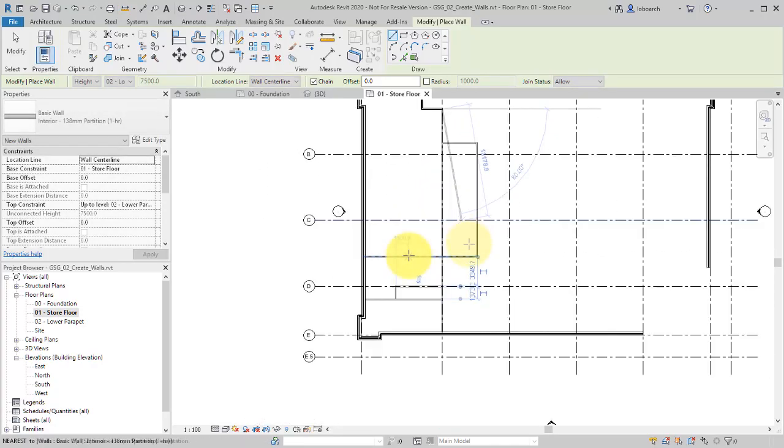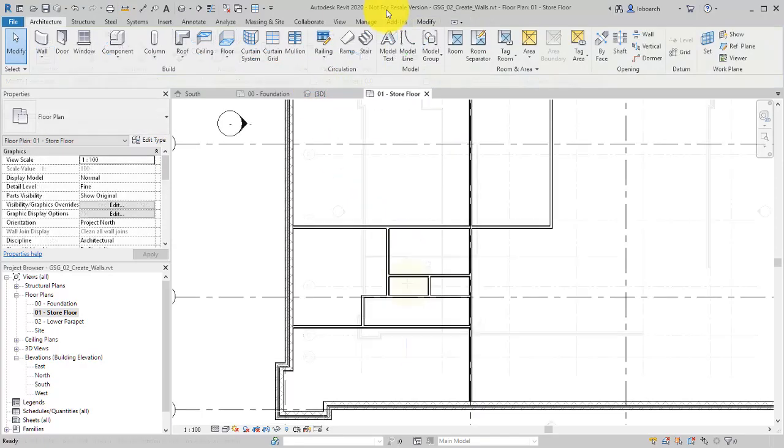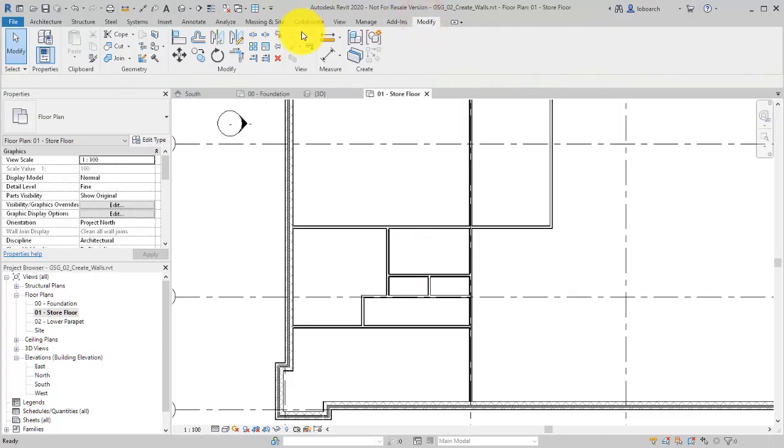While placing interior walls, you might find it useful to change the chain setting depending on the condition where you are placing walls. To create an opening for the hallway, you use the Split tool and split the wall into two separate segments at the point where the opening is needed.